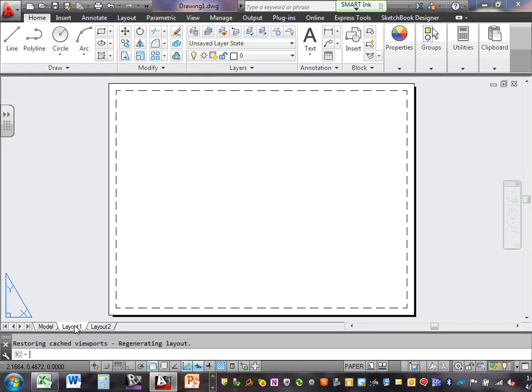When you're ready to print, you grab a printer like this, you size your paper on the right side, pick up the plotter and the printer, and print what you have just finished. We have a plotter here and multiple plotters all over. So that's how we deal. Paper space, we print. Model space, we work. See the difference between them? And you can always toggle between the two.